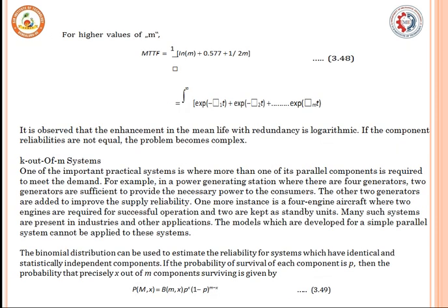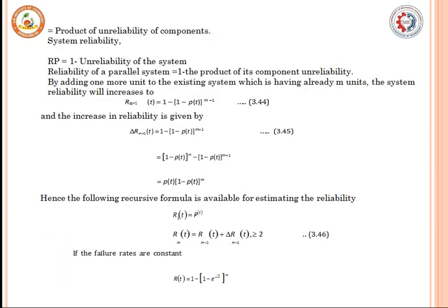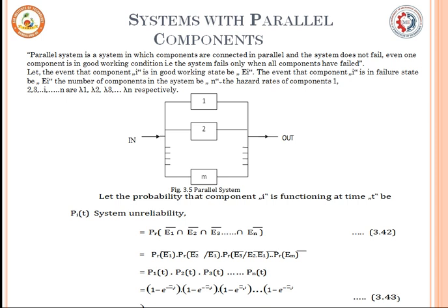Several examples related to the reliability of the system in series and parallel components I'll also be able to do. You'll be able to calculate MTTF and MTBF by using the different expressions. So the system reliability, whether it is in series or in parallel connection, you'll be able to calculate with the required expression very easily.